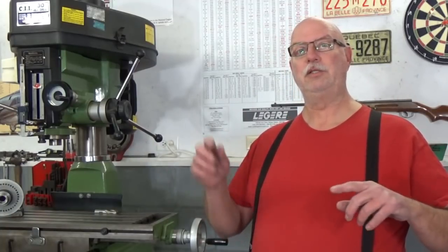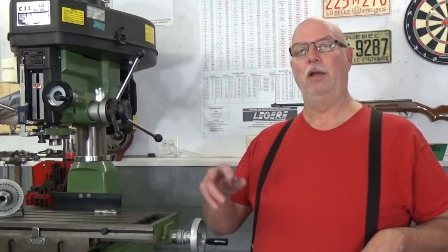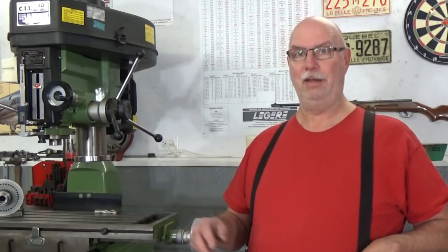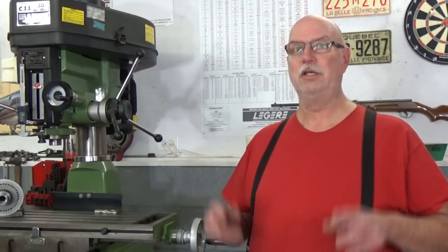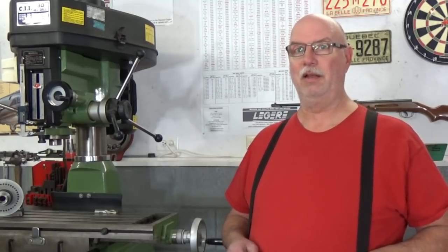So if you have a 1/4 20 thread, imperial, your pitch is 0.05. If you have an M10 by 1.5 thread in metric, your pitch is 1.5. There's no division required there. I hope this clarifies things for you. And if it doesn't, you can go and check out my threading on the lathe video. It could help you with that.